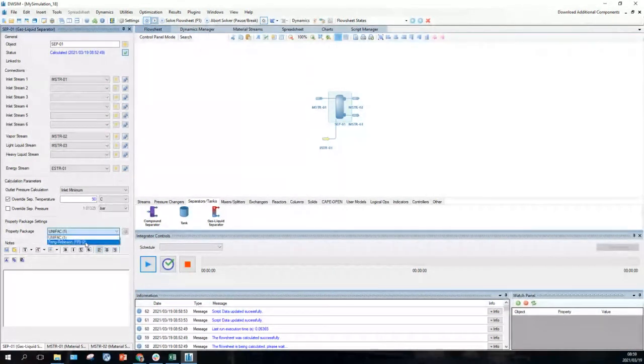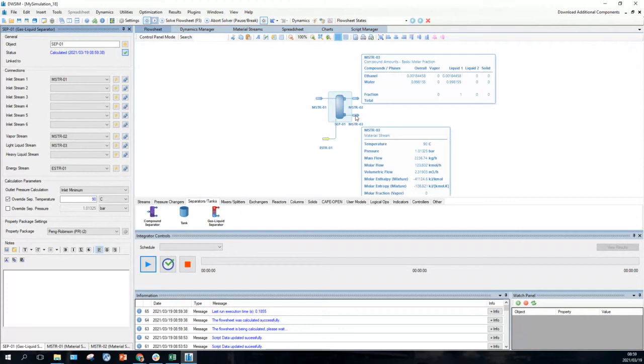Right, because we want the calculation, not how the streams are. And we don't have to accept now, eh? Yeah, it's already run. Just run. And now, because it's going on to the auto run, look at that. There we go. You can see how much that has changed the composition of stream number 3. So now we've got 0.2% ethanol, whereas previously we had something like 5% ethanol.